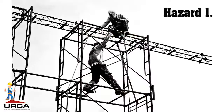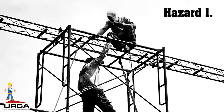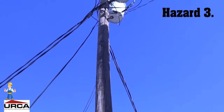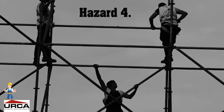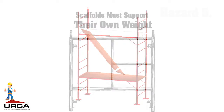Hazard 1. Falls from elevation caused by slipping, unsafe access, and lack of fall protection. Falls may occur while climbing on or off the scaffold, while working on unguarded scaffold platforms, or when scaffold platforms or planks fail. Hazard 2. Employees struck by falling tools or debris. Hazard 3. Electrocution from overhead power lines. Hazard 4. Scaffold collapse caused by instability or overloading. Hazard 5. Bad plank giving way.